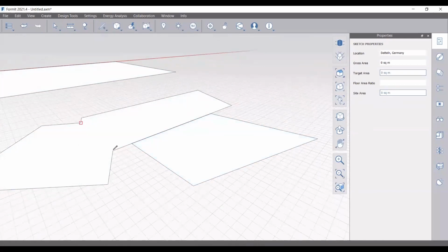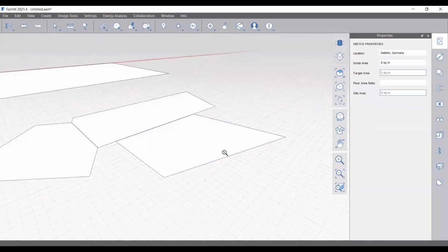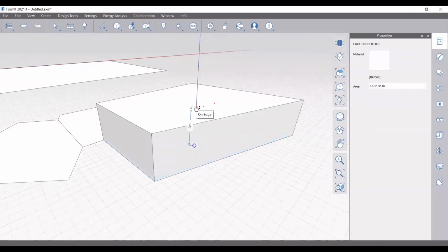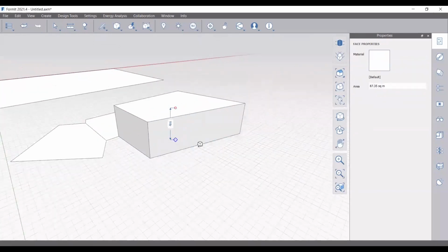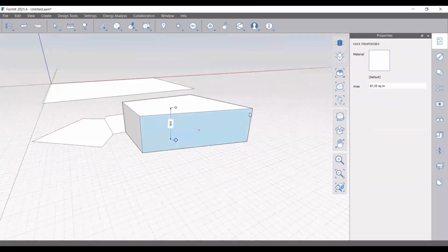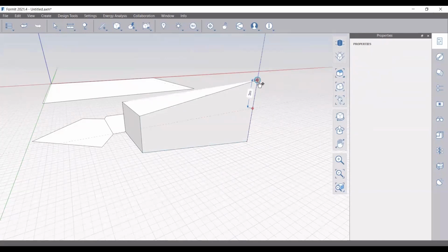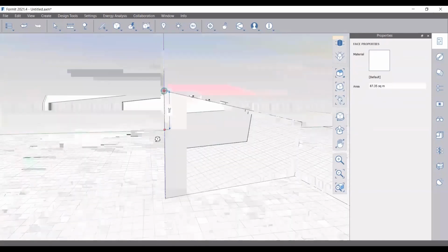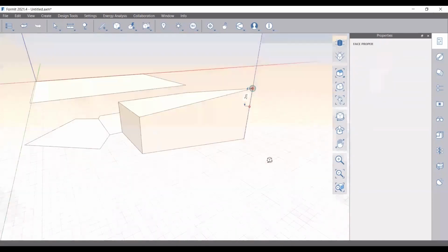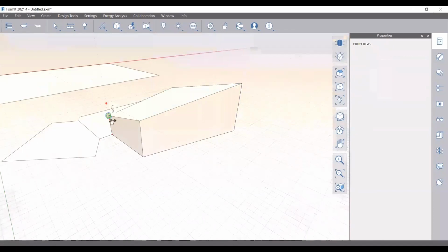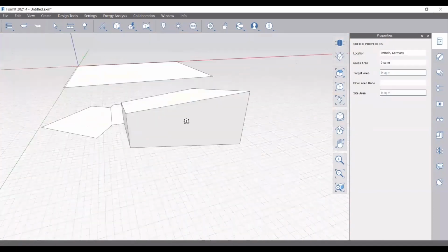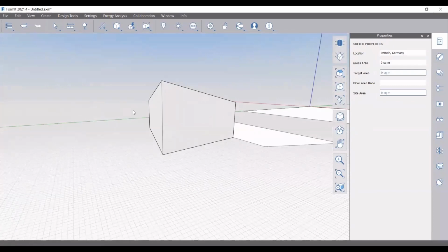And if I want to integrate the surfaces, I can break them through lines. You can say that the one shape has been converted into three parts, and I have extruded this surface to a height of 4 meters. And the more interesting thing here is, when you snap that particular node, you can just pull it and push it to whatever height you want to achieve.